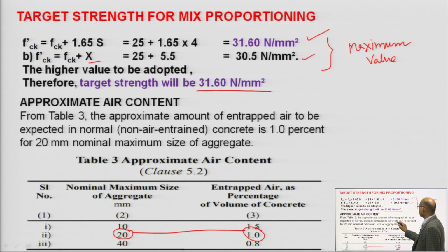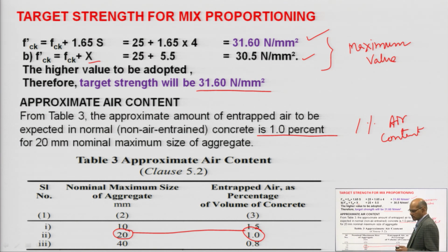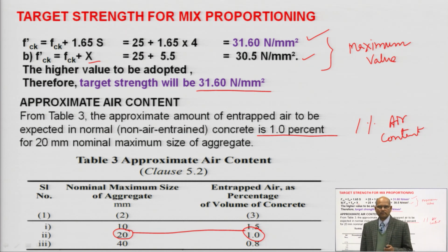We can expect 1% air inside the concrete. So, 1% we have to consider as air content, and that we have to take into consideration while we are doing the mix calculation.